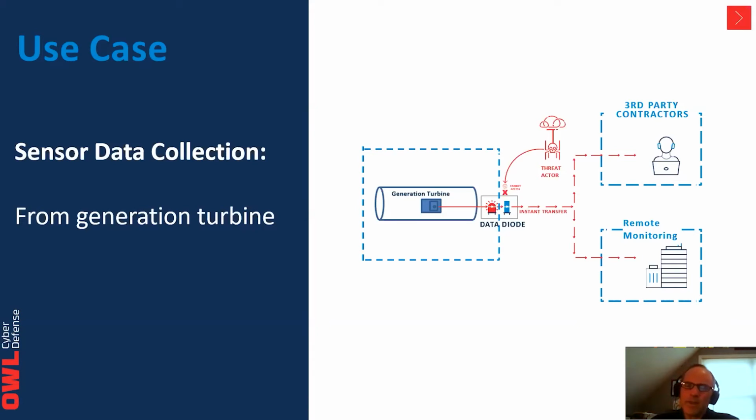The data is generated, and you could have the turbine generating part of that data. You could have some of the data coming from another data source. Stepping back to the proxies we talked about before, if the data type is different, then it may require a separate proxy, and we can run lots and lots of proxies next to each other, managing different data flows and different data types. So a historian would have its own proxy, a TCP/IP connection would have its own proxy, and a UDP would have its own proxy. But if multiple sources are sending different types of UDP data, they would all flow through the same UDP proxy, but as different individual data flows. So you wouldn't have to have multiple UDP proxies running simultaneously.